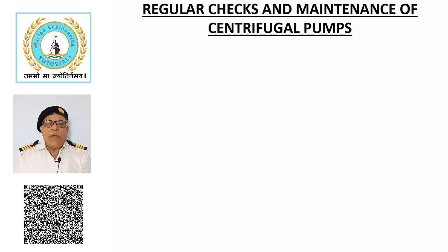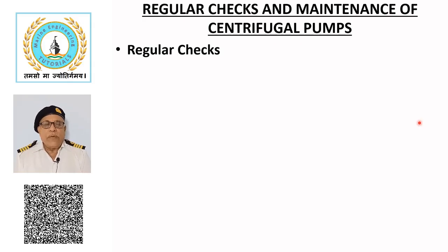Regular checks and maintenance of centrifugal pumps. The following checks and maintenance should be carried out for reliable and efficient operation of centrifugal pumps. Regular checks: noise, vibration, leakage, suction and delivery pressures of the centrifugal pump should be carefully monitored for its reliable operation.